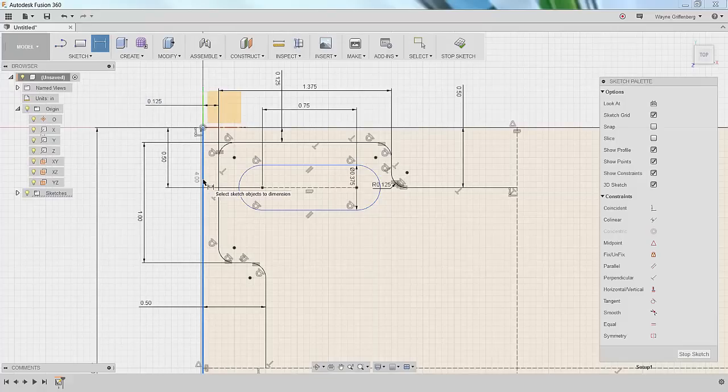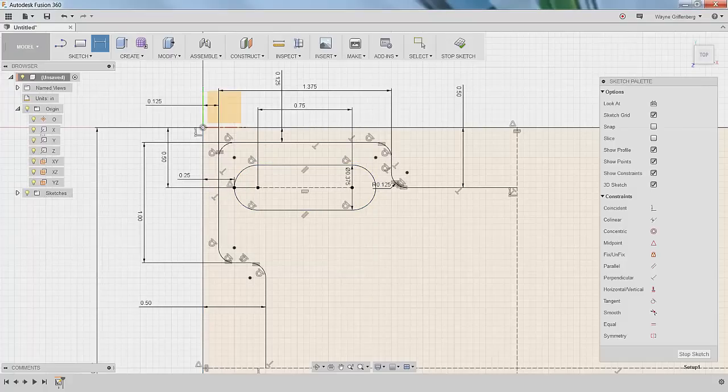I'm going to select my initial datum, hold shift. And now if I hover over, you see it snaps to the quadrant. It'll snap to that midpoint in that quadrant right there. And now I can get a dimension right to that quadrant. And I'm going to make that 1/4 inch. Now, hopefully that's helpful. We thought about that a little bit, but it's great that the developers in Fusion have added that functionality to be able to hold shift and then snap to the midpoint or the quadrant there.